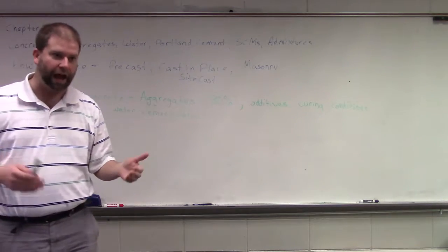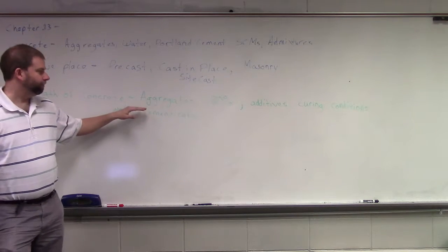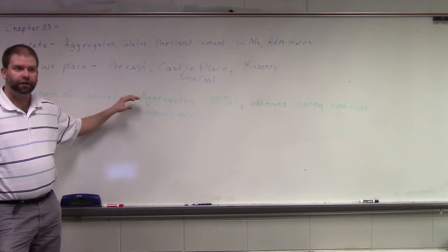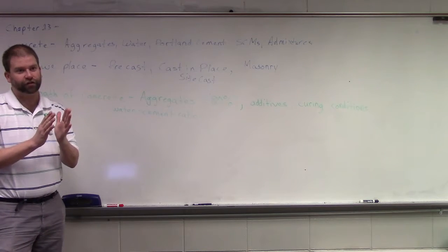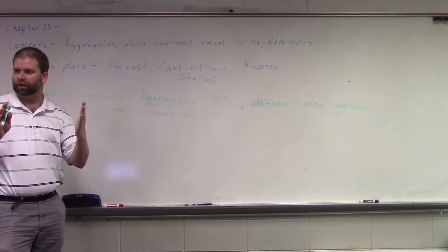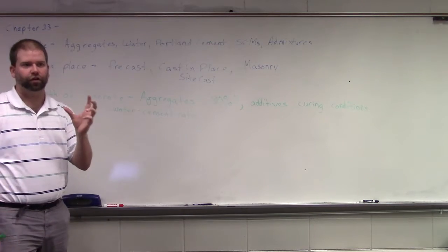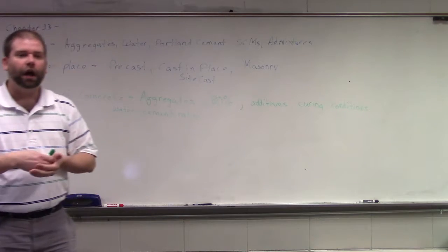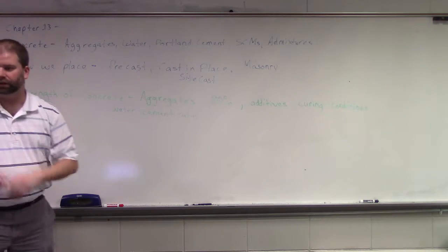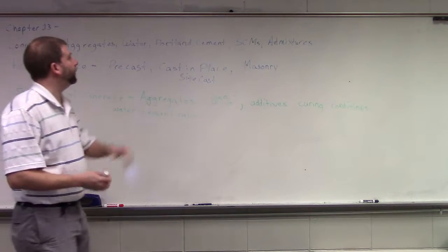So the code has requirements. Obviously you can't have smaller spacing than your largest aggregate, but you have to have a factor of 3 greater than your largest aggregate so that all your aggregate can get through that steel. Okay, so a perfect example of that is, well, we can pull this up quick.